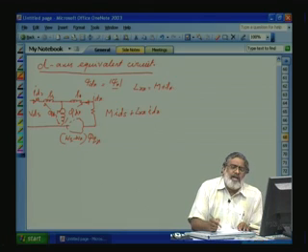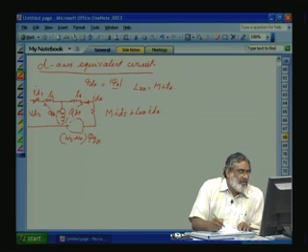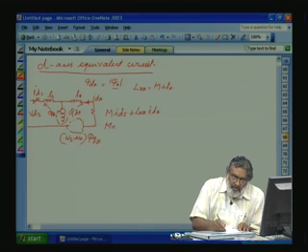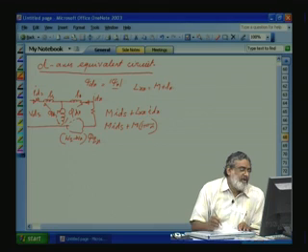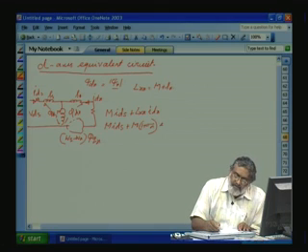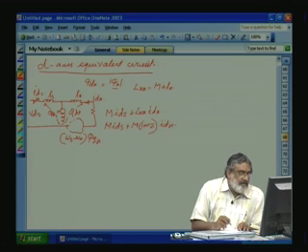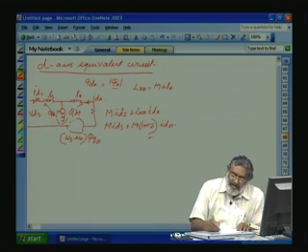So in an induction motor equivalent circuit, leakage is always represented as a fraction of the mutual inductance. So we can write this as M into IDS plus M into 1 plus sigma r. Sigma r is the fraction, 5% of the mutual inductance. So sigma r is a constant, into IDR, okay. This is our psi dr.